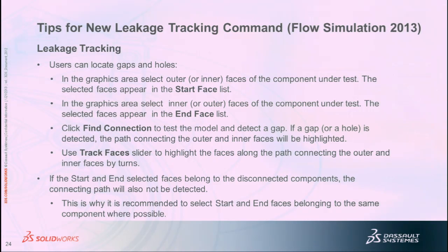Okay. Now the next option that we have here is kind of a helpful feature, and this was definitely a user enhancement request. If you're doing an internal flow problem and you're trying to put a boundary condition on something, it tells you that you can't apply a boundary condition because they can't tell between a fluid and solid region. I don't know if people have done that, if they're familiar with that. And many times that error message means that there is no fluid volume.